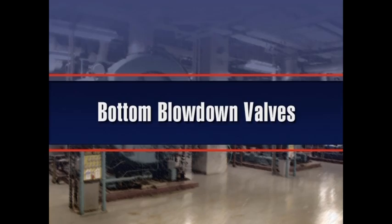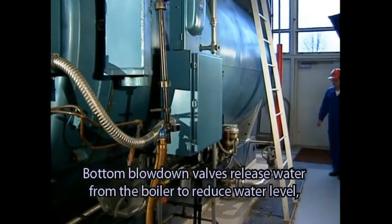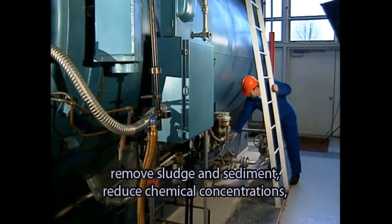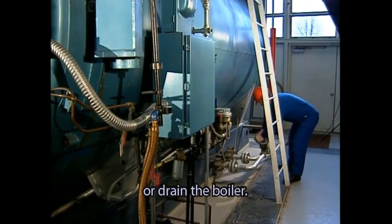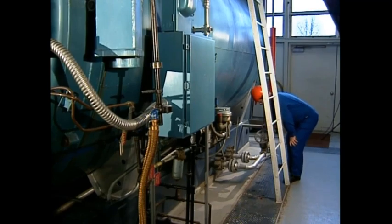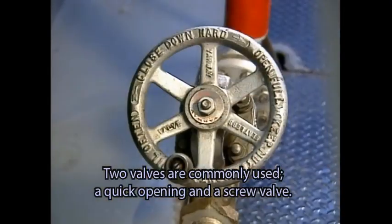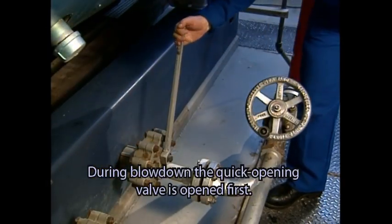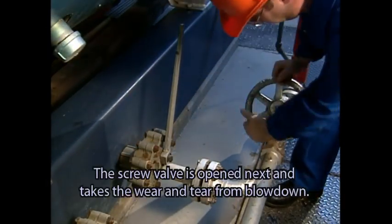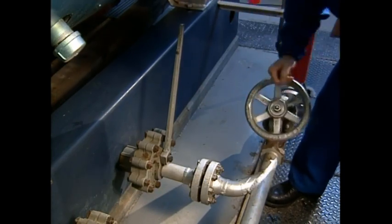Bottom blowdown valves. Bottom blowdown valves release water from the boiler to reduce water level, remove sludge and sediment, reduce chemical concentrations, or drain the boiler. Two valves are commonly used, a quick opening and a screw valve. During blowdown, the quick opening valve is opened first. The screw valve is opened next and takes the wear and tear from blowdown.